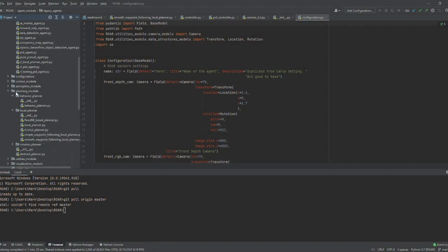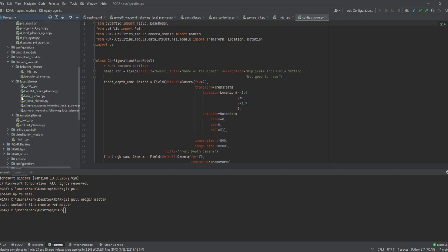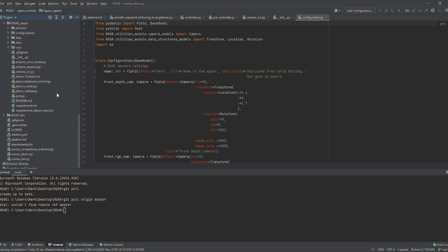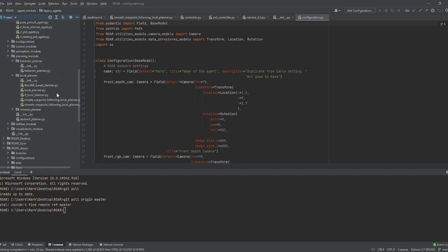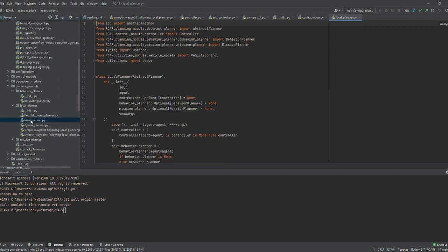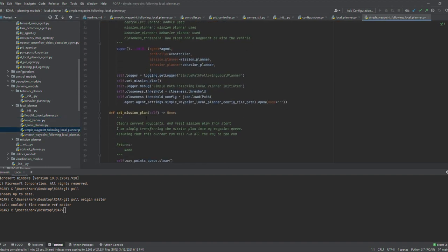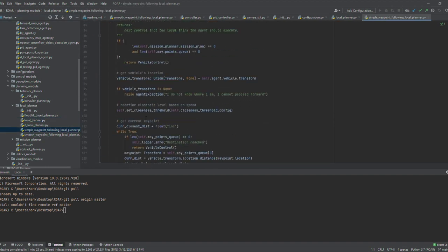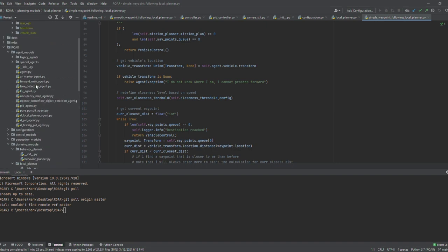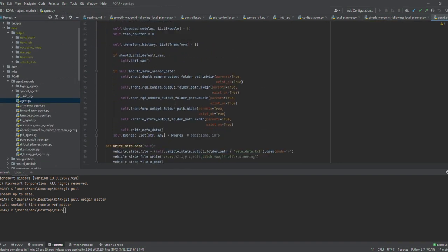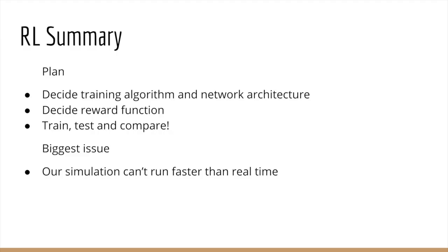The ROAR repo is quite dense and a little difficult to understand structurally at first. Michael is a big help in understanding the structure as he has worked with ROAR for a year now. More digestion time with the system is needed to understand how components work together. For the DWA planner, we need to use the dynamics of the model, as it is assumed in the paper that a robot with synchro drive is used. Our model is a car, but we can use a bicycle model to simplify things.